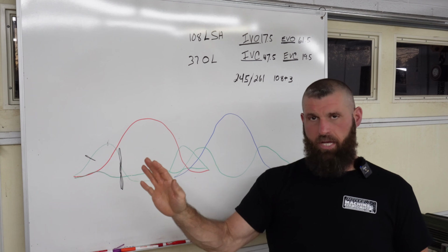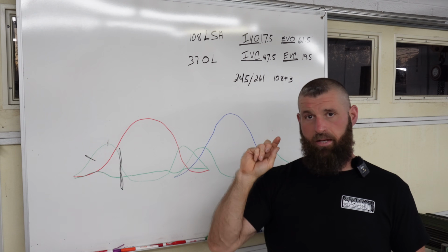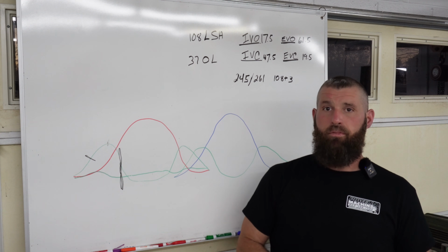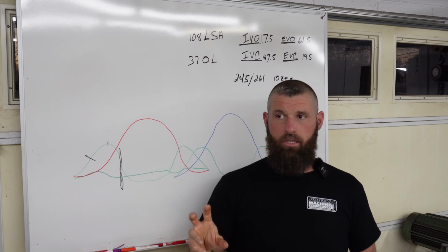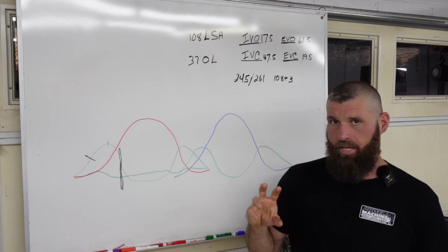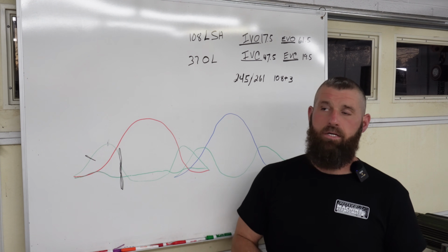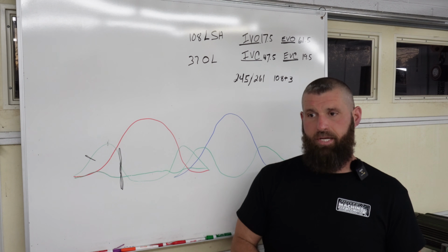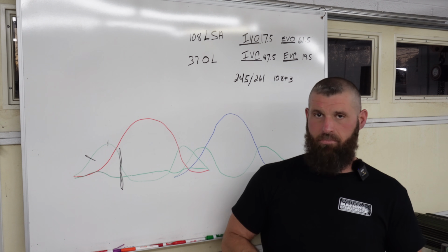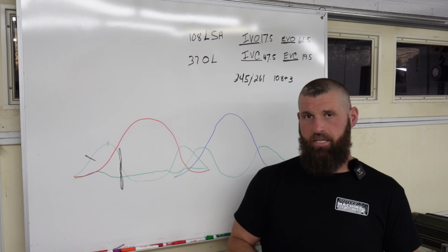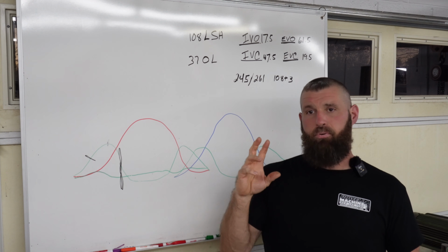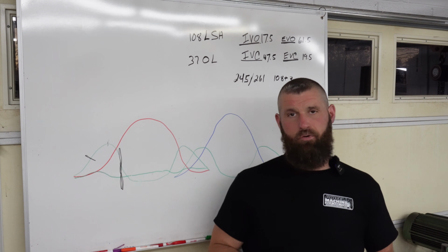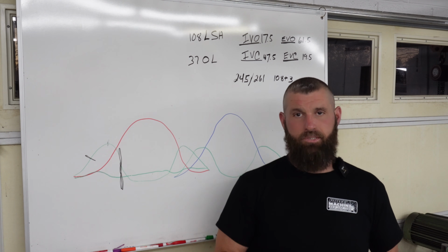The curve would look identical, and you could do it with 12 degrees less. That is the beauty in a lot of applications, and we see this all the time, especially with big blocks or anything with big cubic inches. People buy a cylinder head that would be a really good head for a small block Chevrolet and put it on a big block Chevrolet.